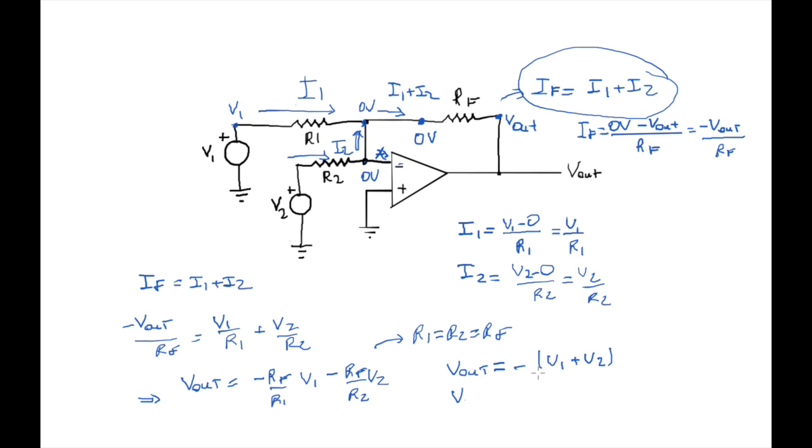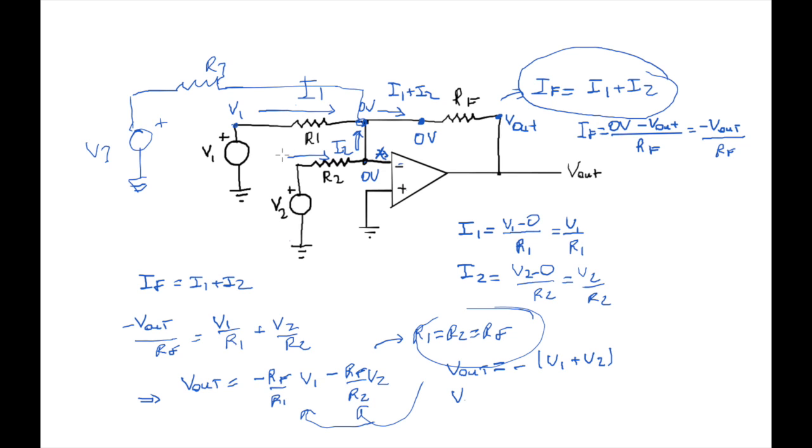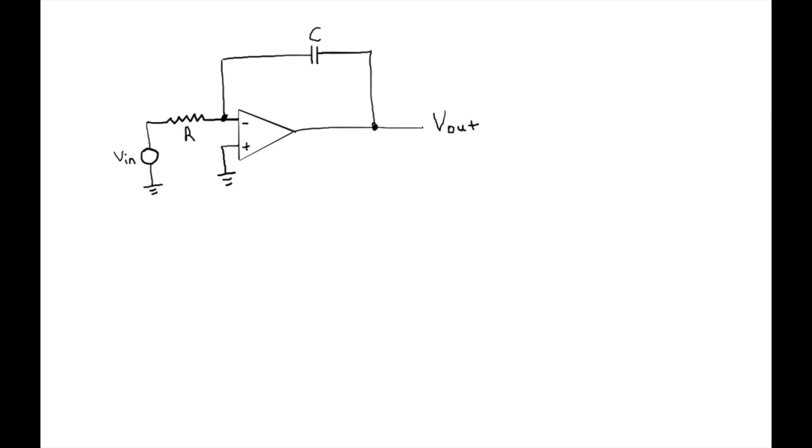And of course, this is just a simple summation in this particular case, but I can obtain any linear summation between V1 and V2 by using this circuitry. Now, if I had 10 such voltages, I could have just put them in parallel. For instance, let's say I have a V3 here. I can just easily connect it to this circuitry from the same point, and it will be another factor in my formula.